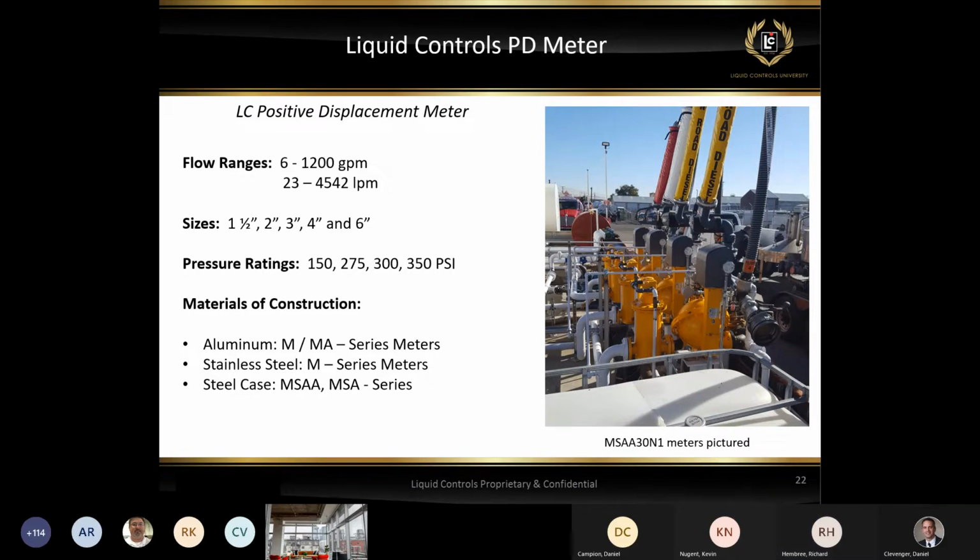But something you should always keep in mind, and this question comes up very, very often, is: I want a 1.5 inch or a 2-inch or 3-inch meter. We have multiple flanges that can be added to a different meter, so we can actually have 4 different meter sizes that can be considered a 3-inch or a 4-inch. So don't always size the meter based upon the pipe diameter or the inlet diameter, but size the meter based upon flow rate. We have pressure ratings for our meters.